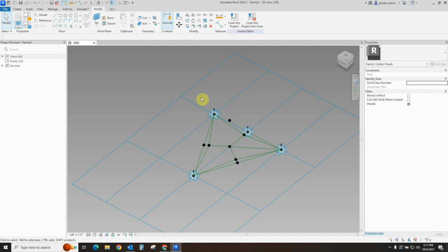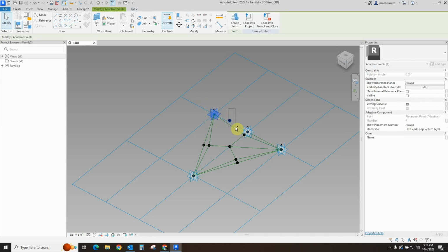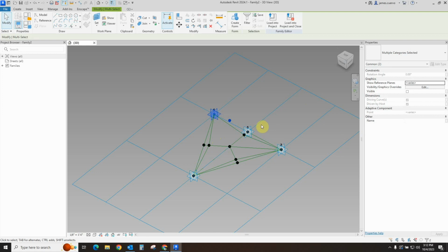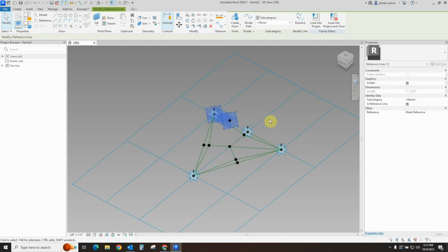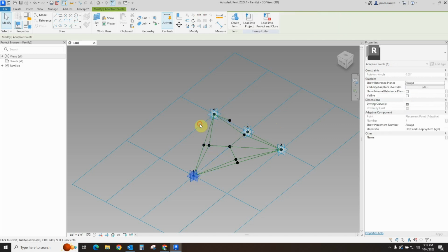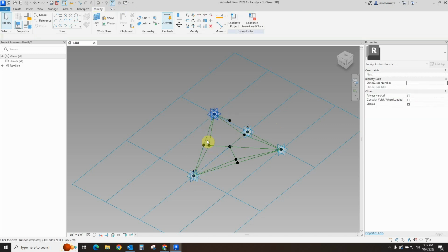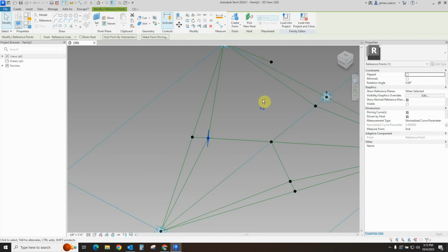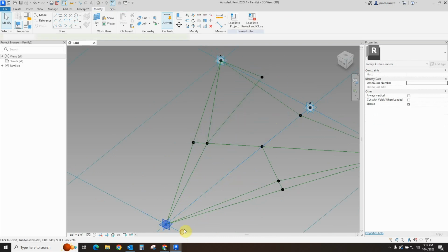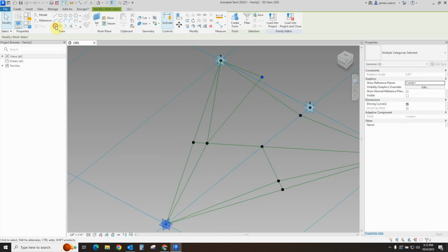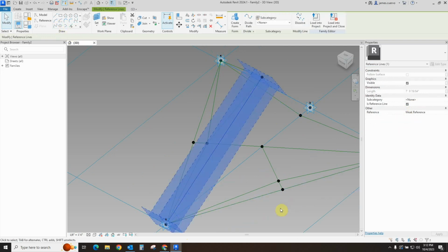Okay, so let us begin by selecting this point and this one up there, which is the one that we have given 4 feet. Select spline through points, and there's my point, and we'll convert it to a reference line. Okay, we will then continue with this point here, or rather, let's go ahead and make it sequential. This one, now we'll do this one here. I've got to get a little bit closer because it's going to be between that one and that one. Okay, create point. It is a reference line. We will repeat the process just like this. There's another one, a reference line.